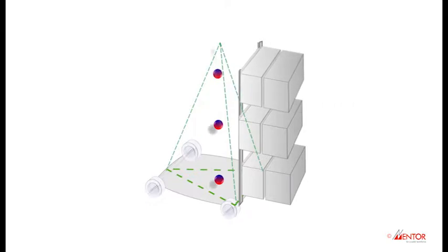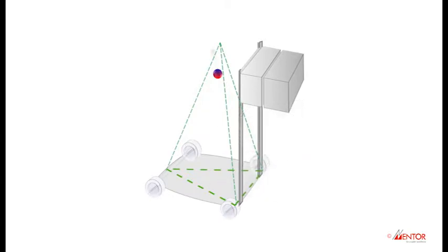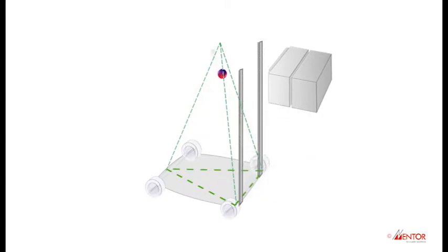of the stability pyramid. When operating a reach truck and extending the reach, you can see how close the centre of gravity is to the edge of the stability pyramid. That means any actions of bad practice have a much higher risk of the lift truck tipping over.